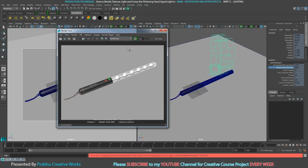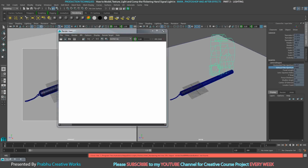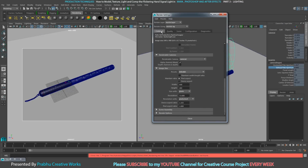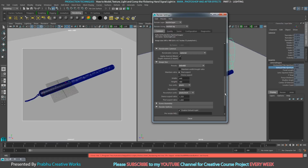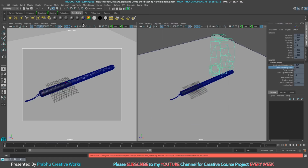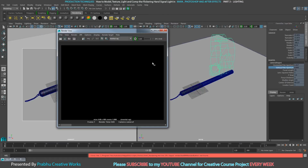See, I have not set any light in our scene, but we have lighting showing up because in render settings, here in the common tab under render options, you want to disable enable default light. So I will click this one and click render again. Now you cannot see anything in the render because I disabled the enable default light option. So that means we want to set light manually.